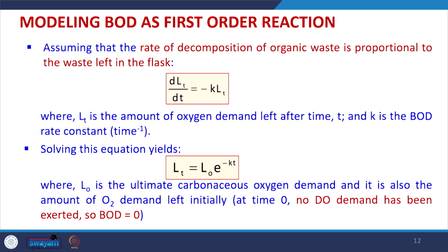So, we have learned that the BOD can be determined by 3 methods. Under one case we do not require any dilution water, and we essentially determine the BOD value using the initial DO and final DO. In the second case, the water sample may have to be diluted if the value of BOD is a little higher. Under those conditions we use dilution water which does not contain any microorganism. In the third case, microorganisms may be required because the water sample may not contain any microorganism by itself. So, under those conditions we use dilution water which is called seeded dilution water, and which itself incurs some demand for oxygen. Under those conditions we use this formula for determining the BOD value.